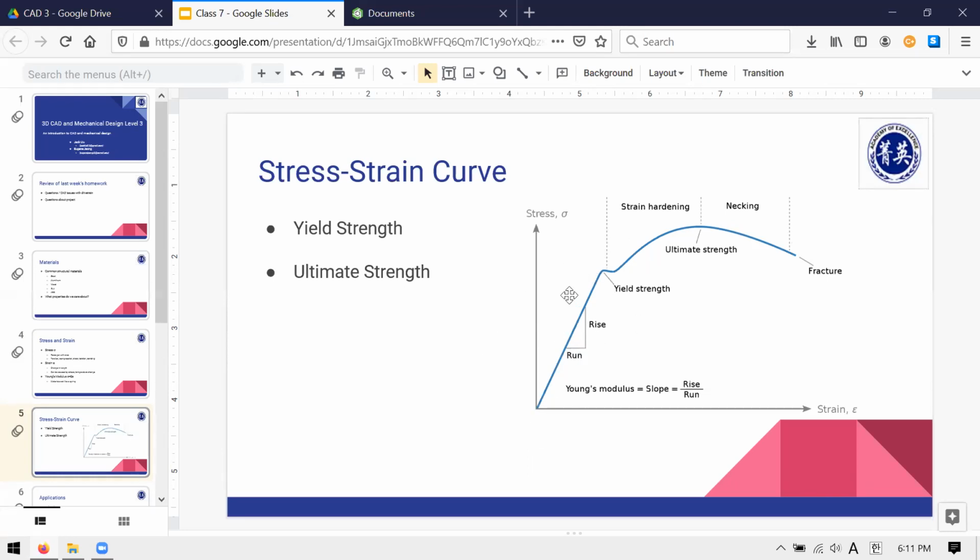And so this is called the elastic region because materials behave kind of like a spring when in this region. So if I have a piece of metal, you don't usually think about metal as being something that bends a lot or easily, but at a very small scale, if you apply force to a metal or any object that's elastic, it'll get longer a tiny bit. And when you let go, it'll spring back into its original shape. So that's what happens in this first region.